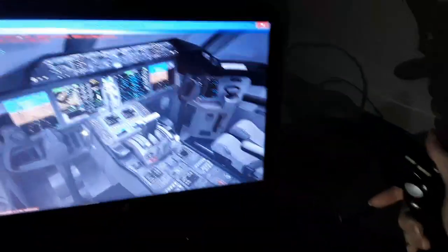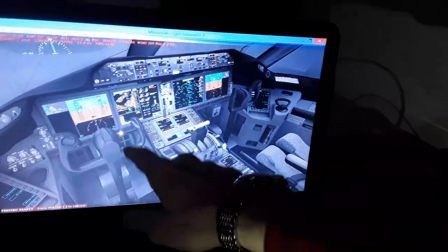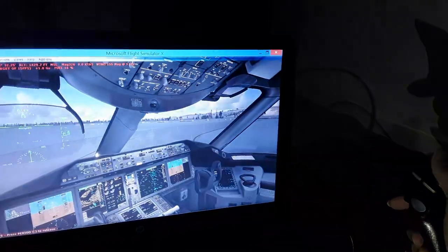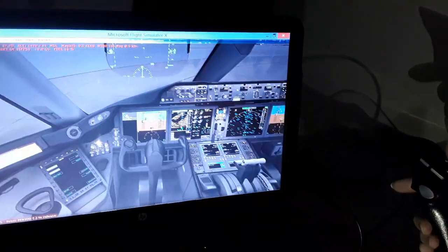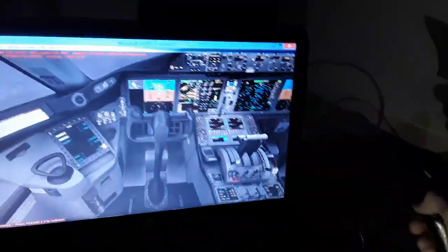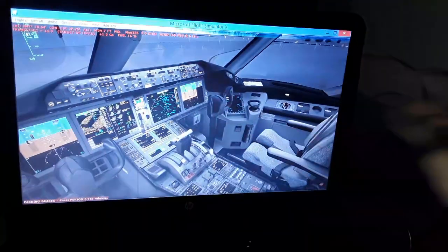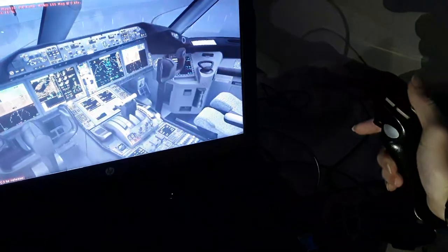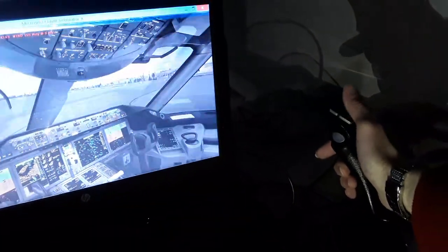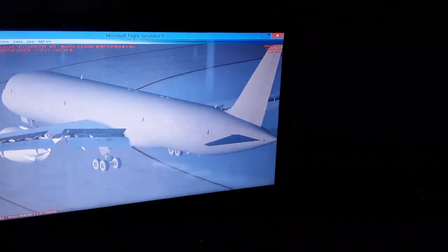Also we have the rudder pedals. The rudder pedals we use for controlling the vertical stabilizer rudder, and also the nose wheel steering. On the ground at low airspeeds we have also the tiller on either side. Also rudder pedals on both sides, as you can see, are interconnected and move together. Both Boeing and Airbus aircraft have similar design.